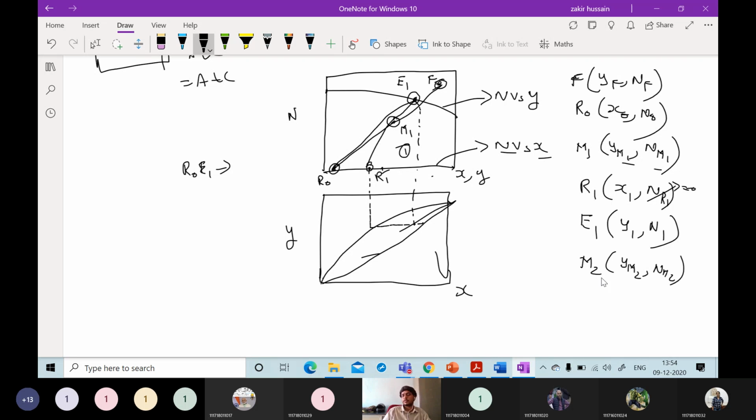You have to estimate it using the material balance for stage 2. Then that will be falling on this line, so this will be M2. Similarly, you have to draw a tie line. The tie line you can draw using some guess value, which is projected until the equilibrium or distribution curve, then projected until the diagonal line, then these two points have to be joined. If M2 comes on that tie line, that tie line is correct. So this is called stage 2.